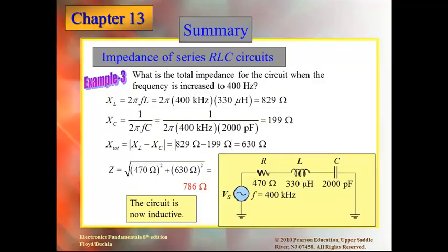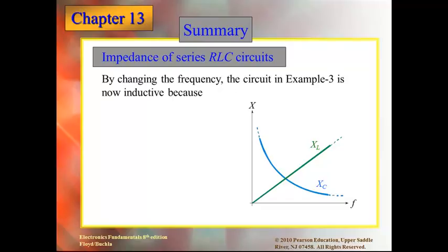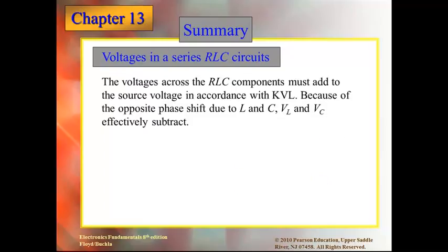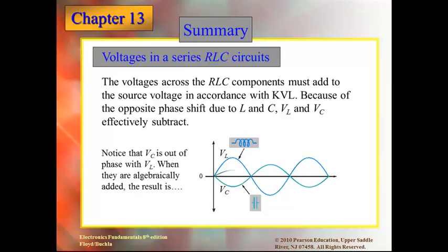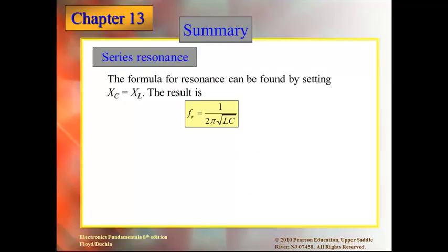And so, again, we need to remember that a little bit, because it's just as bad for us to overcorrect as it is for us to undercorrect. So we need to keep track of that when we're calculating. Very seldom do we ever calculate all the way to 100% on power factor correction. And Kirchhoff's voltage law tells us we can balance those things out. And ultimately, that's what we're looking to do, get them very close to zero input or zero contribution, I guess you'd say,